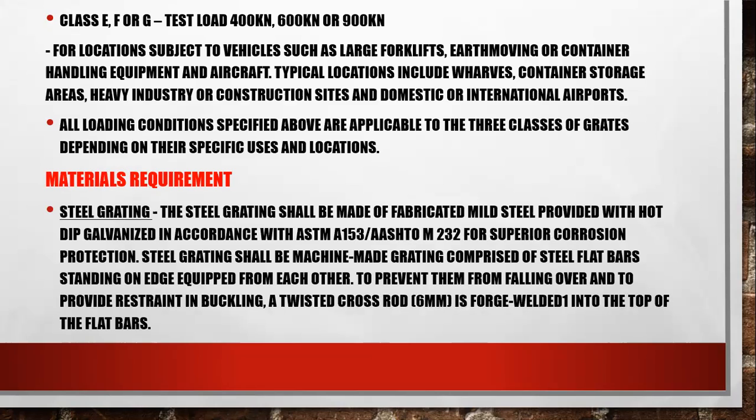So the material requirement, first, is the steel grating. Steel grating shall be made of fabricated mild steel. From the word steel grating, we should use steel, provided with hot dip galvanizing in accordance with ASTM A153 and A123 for the protection of corrosion.